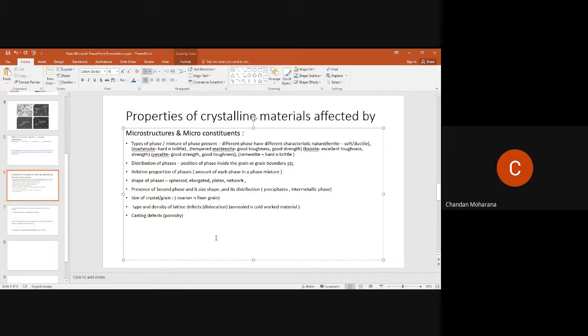So during this, dislocation annihilation occurs. Annihilation means they disappear from the material. But during cold working, a large amount of dislocation is generated. Do you remember what the source of dislocation is? How do they generate? Frank-Read source. The dislocation is moving, then it gets pinned at both ends. Now you are recalling the figure. So that is multiplication of dislocation.